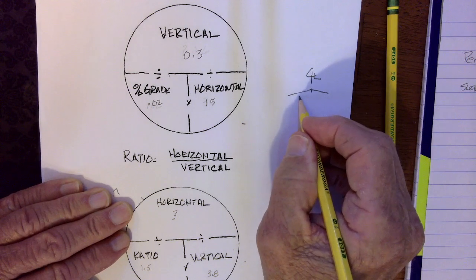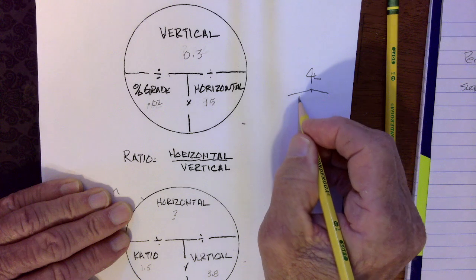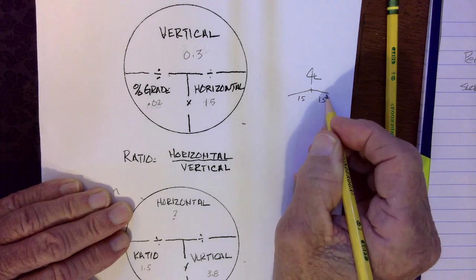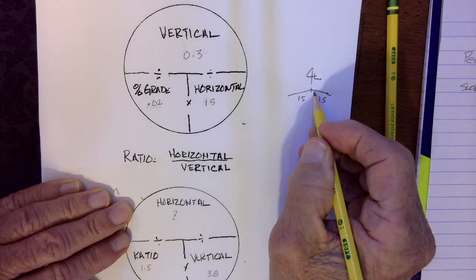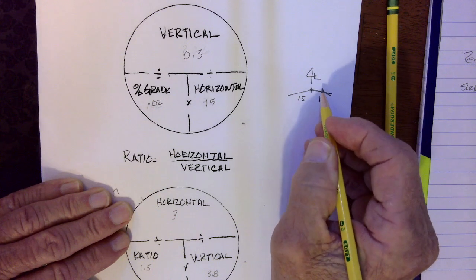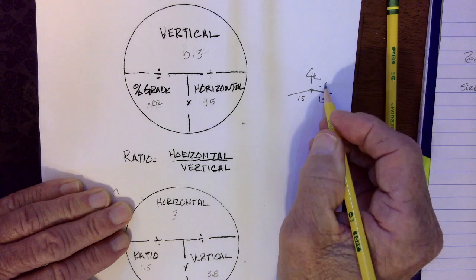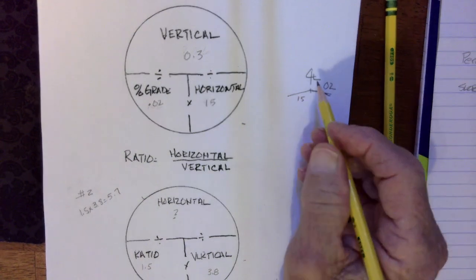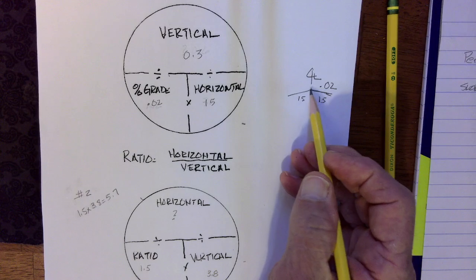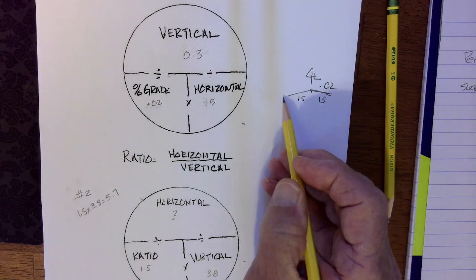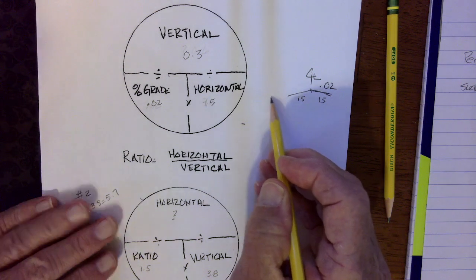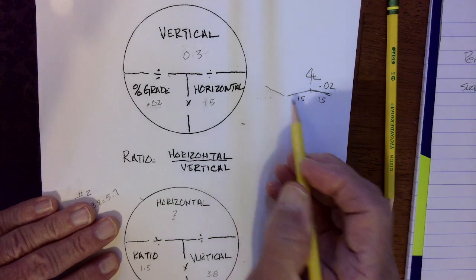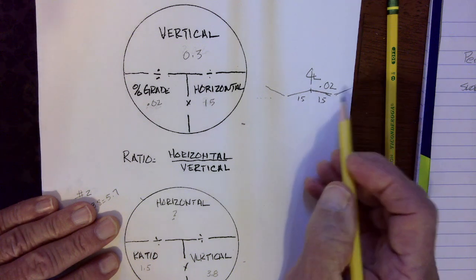This over here is 15 feet. This over here is 15 feet. And what I'm after is, I know to shed water off this, I need a 0.02 fall or 2% fall. So the way I'm going to find out my elevation right here, let's say this is a back slope coming down, and this is a back slope going this way.